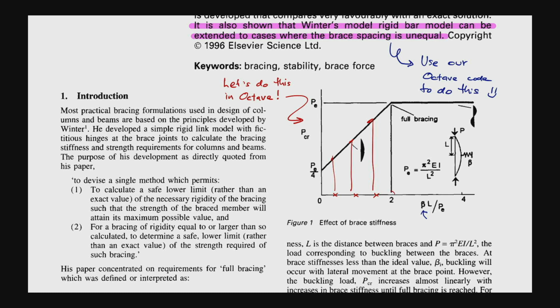Once we come to the ideal stiffness, then we get to the number of the anticipated buckling load. When we provide more and more stiffness to the system, you cannot get anything better than the buckling load. That's because the full buckling has been developed, and you will not get anything more than that. So that's the fact.